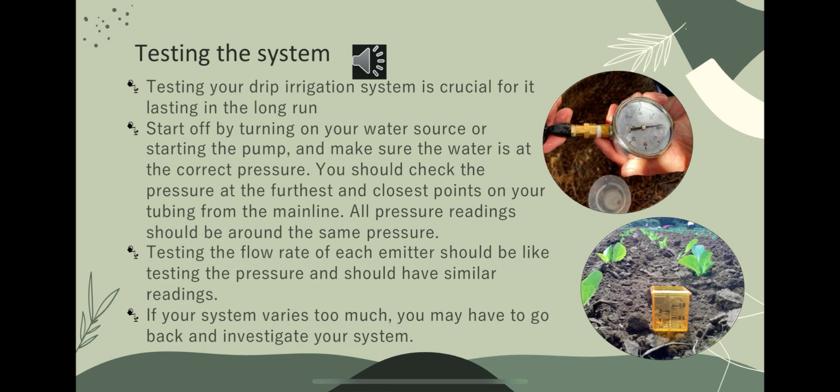Testing the flow rate of each emitter should also be like testing the pressure. You should have similar readings. If your system varies too much, you may have to go back and investigate your system for any problems. Testing